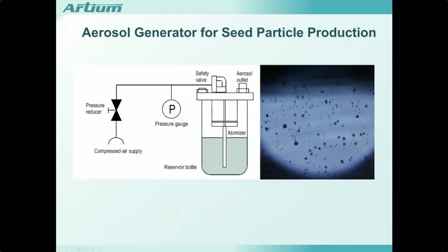I'll just run through a few particle generation means. At NASA, I built atomizers, essentially Laskin atomizers. You have a tube and a pressure vessel. The liquid would climb up the tube due to the Bernoulli effect, blowing high-speed air past a small orifice. The liquid would come out, pre-film, come out, be blasted by the jet and atomize.